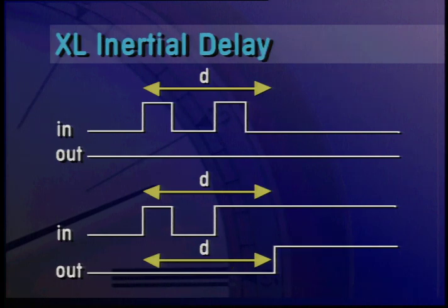In Verilog's second delay model, called the XL model, the event is simply left on the list, and the new value is propagated at the old time. In the vast majority of cases, this results in the same model behavior at a considerable saving of time. In summary, the semantic restrictions imposed by the HDL, or not imposed, can make a significant difference in simulation speed.